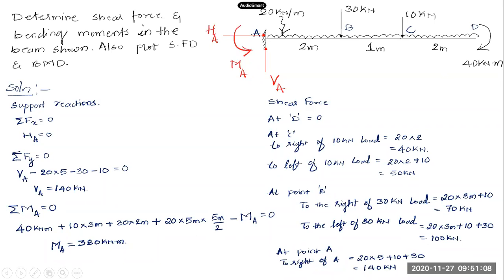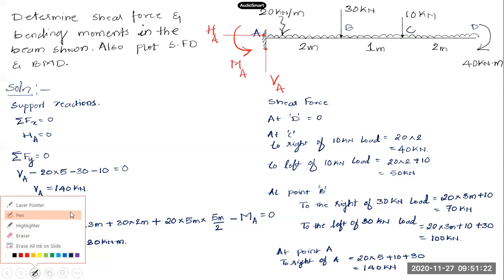So this couple will not come into the picture when you are calculating the shear force value. This will not do anything to your shear force, so the shear force values are unaffected. So these are our shear force values. Now, what about the bending moment values?